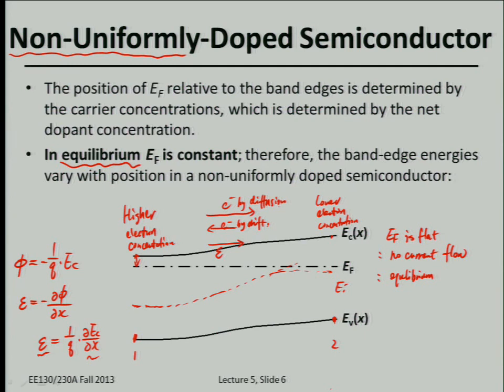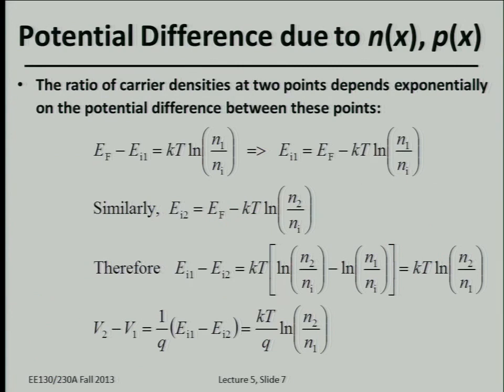The two current components flow in opposite directions. In the following steps, we want to find the potential difference along the semiconductor to perform some deeper analysis of the relationship between the two. But qualitatively, diffusion current has the opposite sign to drift current in an equilibrium semiconductor, okay.